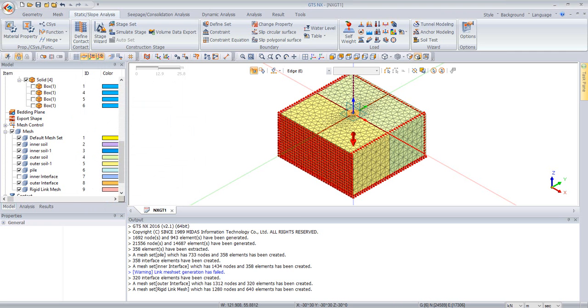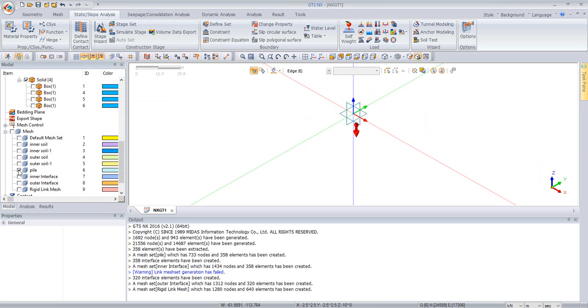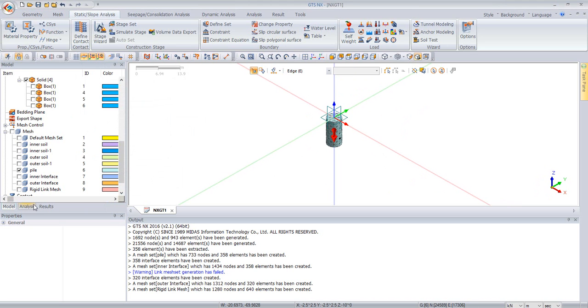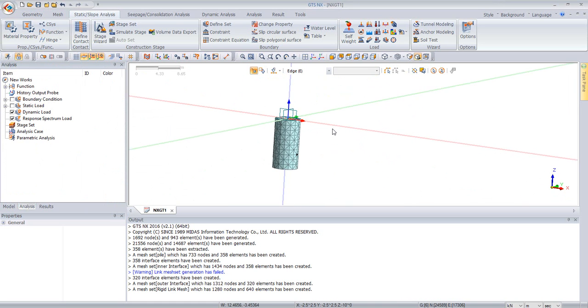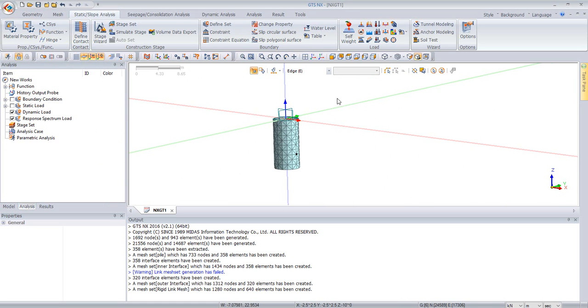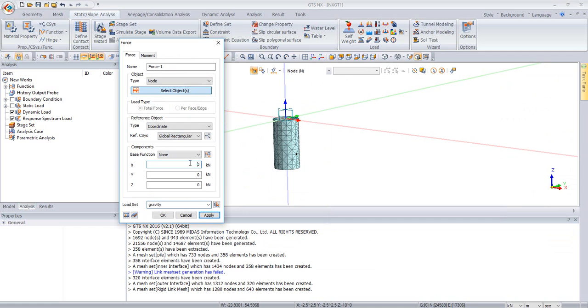And now we're going to get very specific with the point load. As we had mentioned, we're going to apply a force specifically to model the interaction with the chain, the pull force from the chain itself. We're going to create 4 sets of force loads, and we're going to vary the magnitude in the x and z direction to create different angles of pull. So we're going to create one first at 30 degrees.